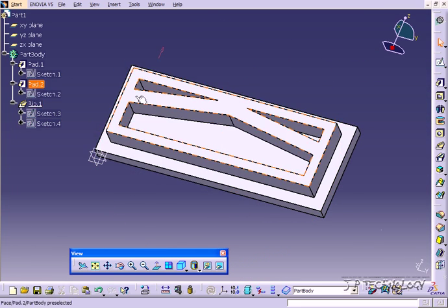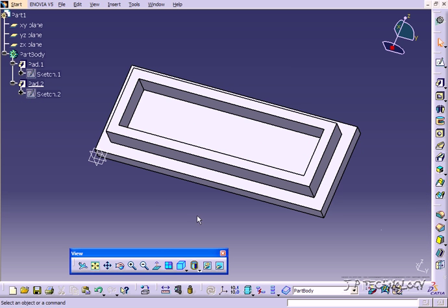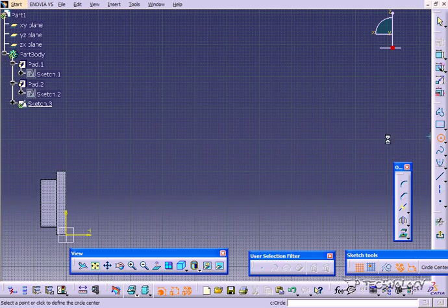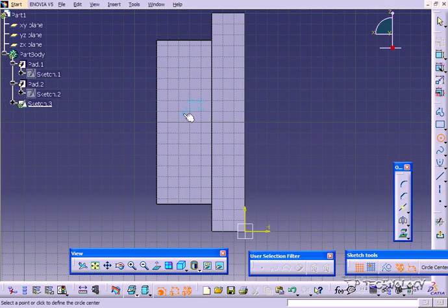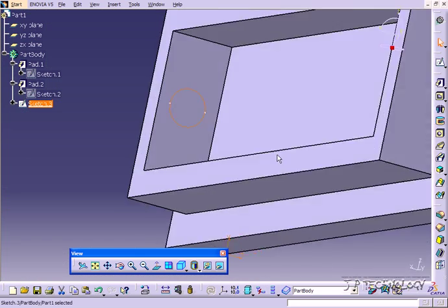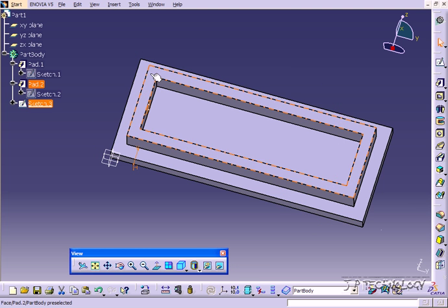Now we've been able to successfully make a square or rectangle follow this path here. Now we're going to try a different shape. So let's just delete this rib right now. Click OK. And we'll click this face here, click Sketch, click the circle, and just draw a circle anywhere inside of here. And we'll go back up, and we'll make another path for it to follow.